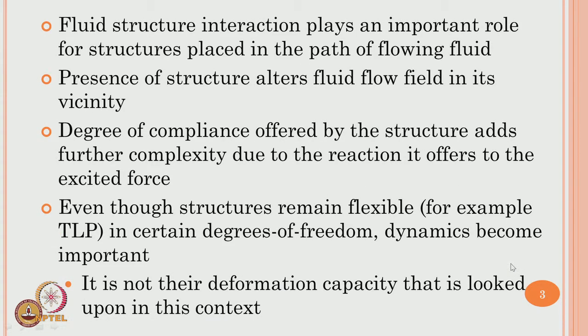Having said this, we must understand that fluid structure interaction plays a very important role for structures placed in the path of flowing fluid. The presence of structure significantly alters this flow field in its vicinity, that is very important. Now, depending upon the diameter of the member versus the wavelength effect, what we call d by L effect, etc., the significant alteration of the structure in the fluid field may not be present. So, what we mean to say is the structural presence is felt only within its vicinity.